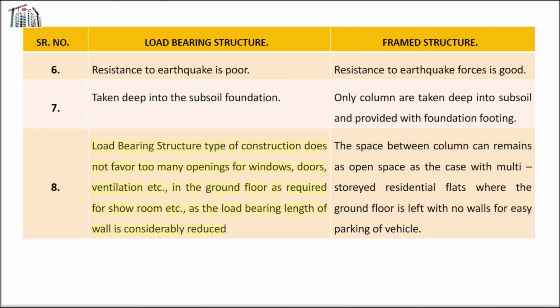8. Load-bearing structure type of construction does not favor too many openings for windows, doors, ventilation etc. in the ground floor as required for showrooms etc., as the load-bearing length of wall is considerably reduced. The space between columns can remain as open space, as is the case with multi-storied residential flats where the ground floor is left with no walls for easy parking of vehicles.